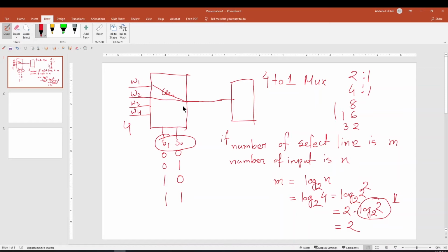If you have more logic gates, it becomes more complicated. So if you can solve it with a multiplexer, it's best to use the multiplexer. You can also implement various circuits using only MUX. In the future we will talk about adders, and you can make an adder system with a multiplexer. Mostly it is used for data selection: if you need to select from multiple data to one line, a multiplexer is often used.